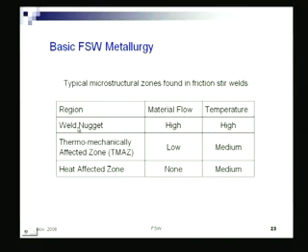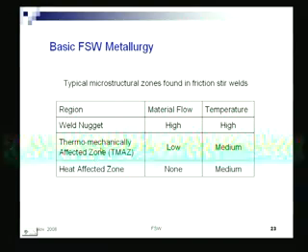Within that is the weld nugget, wherever the welding takes place, where both the plates have got the so-called metal stirring, and the so-called weld deposit has formed. That is the weld nugget, within the thermomechanically affected zone. That means this part is thermomechanically affected. In welding it was only fusion and then heat affected. Okay, so a little more we will see tomorrow.